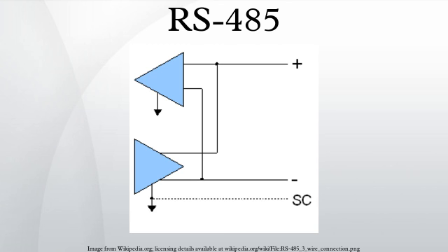Connectors: RS-485 does not specify any connector or pin-out. Circuits may be terminated on screw terminals, D-subminiature connectors, or other types of connectors. Pin labeling: the RS-485 differential line consists of 2 pins. A, also known as minus, also known as TXD-/RXD-, also known as inverting pin.